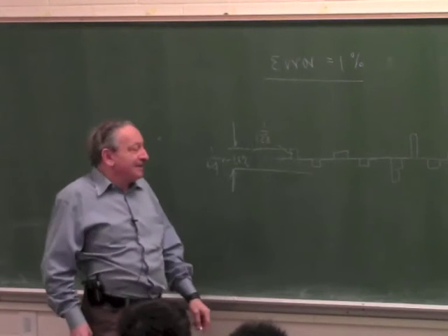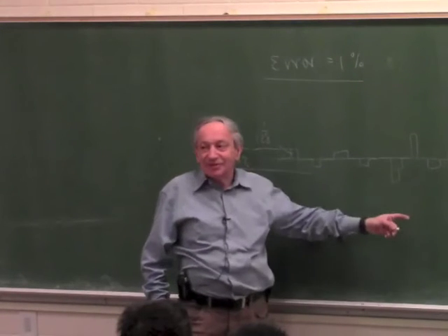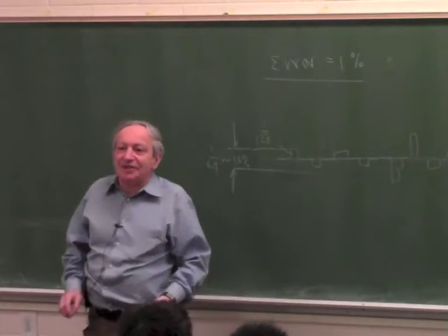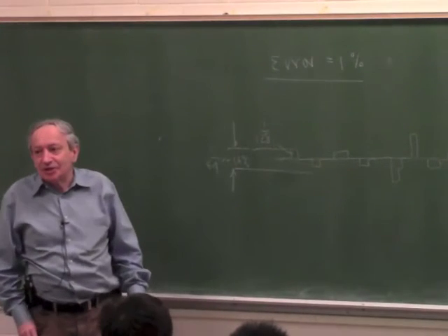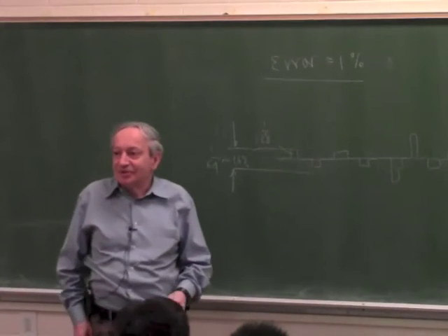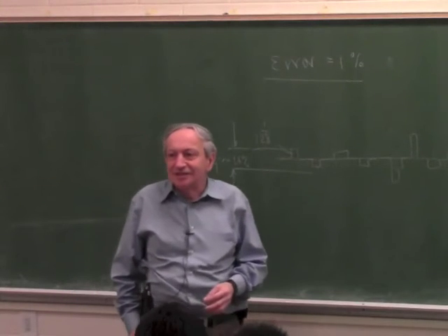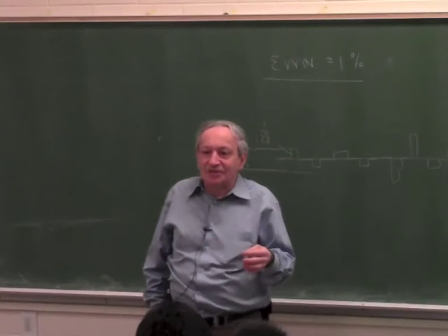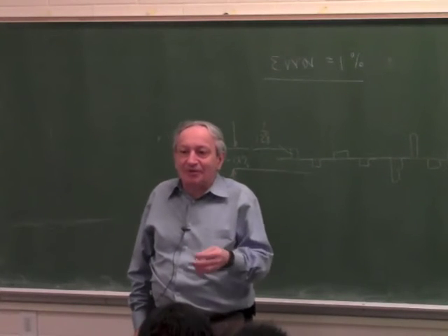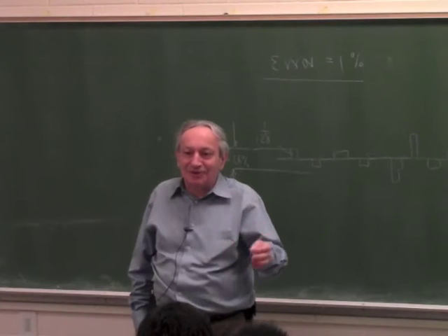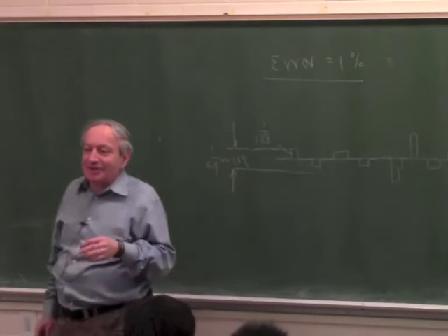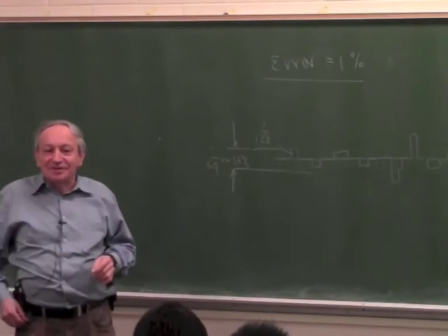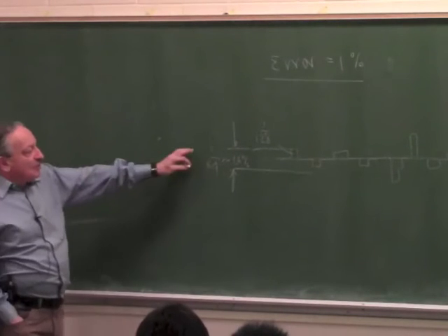But in reality, it will do this many times. So if you absolutely need a servo to hold the total error to 1%, probably 8 bits is very marginal. You would go with a 10-bit system or 9-bit system. 9 doesn't exist. Most of these A to Ds and systems go 8-bit, 10-bit, 12-bit, 14-bit, 16-bit. So it's not a standard number, a 9-bit A to D or system. But that's only when you deal with digital.